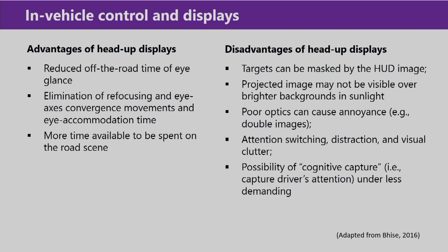Then attention switching, distraction and visual clutter. While the driver is looking at the road, in the same visual area or view field, when these types of images are projected from the head-up display, it may create visual clutter and it may also lead to visual distraction from the primary scene. Then there is the possibility of cognitive capture, that is, it captures the driver's attention under less demanding conditions.